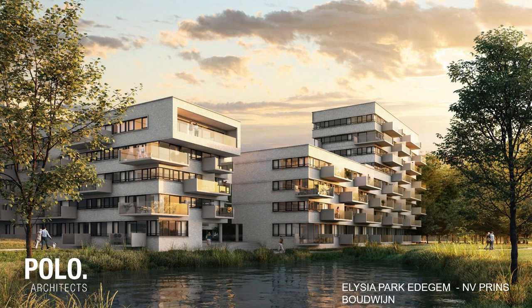Yeah. Well, that's fine. I think the whole product, BIM 360 Design, has so much to it, yet is very easy, but people have to start somewhere, right? If you're used to working with central files, save to central, reload latest, that's the first step, and that's what I would advise. It's what you're used to, and you can bring that forward into BIM 360 Design as well.